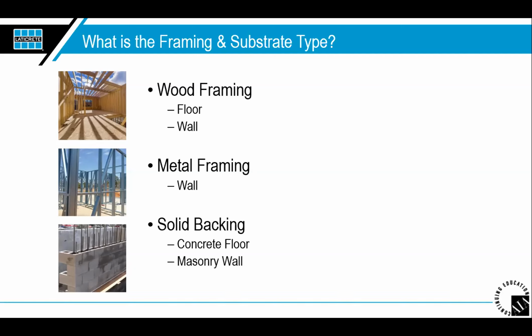Some joist spacing could be 16 on center, 19 on center, and then now we're seeing them as close as 12 on center, and sometimes we've actually seen it even closer, just depending on where the building is being built and what the ownership actually wants out of that building, and what we're going to install on top of it, how tall it's going. So uncoupling, for example, is getting very, very popular, and I believe it is talked about later in this slide.